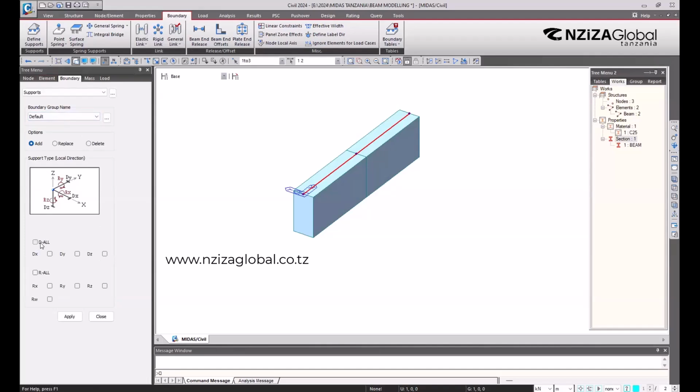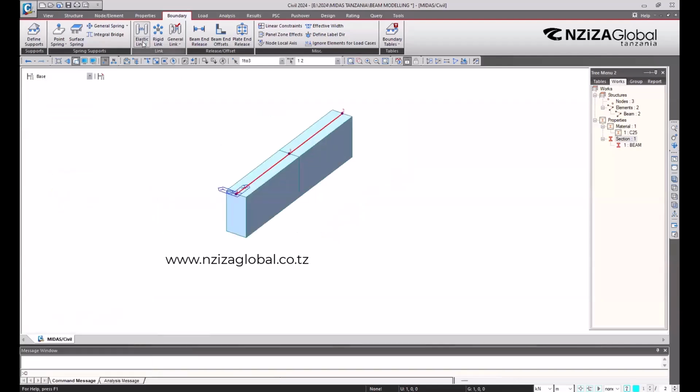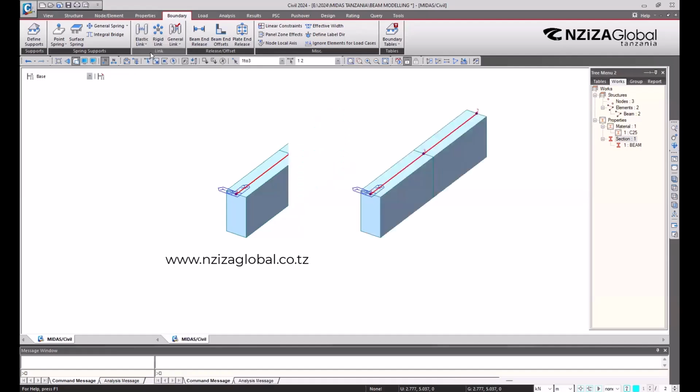We can restrain all displacement in X, Y, and Z, and we can restrain the rotation. Right? Here, I was saying, where the abutments and pier caps are meeting with the decks or beams, we need flexibility, right? Because the deck needs movement. There are rollers. You have the bearings.